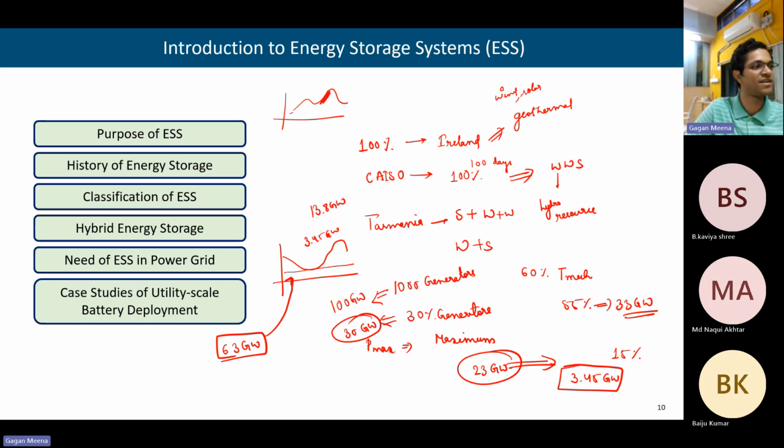Then it is difficult. And out of this, if some generator goes out somehow, then it will be more difficult. And for that, we have hydro plants, so we can schedule some hydro plants. We do schedule hydro plants during peak hours. Also, we have gas plants, which have a very high ramp rate. They are peaking plants, but they are very costly.